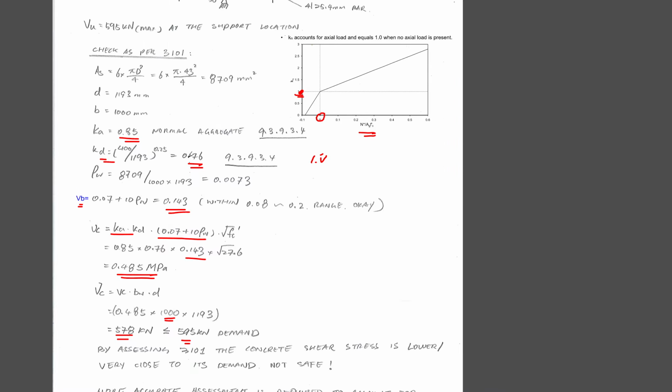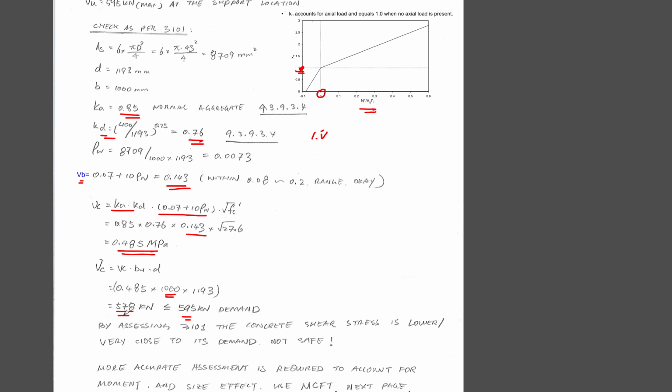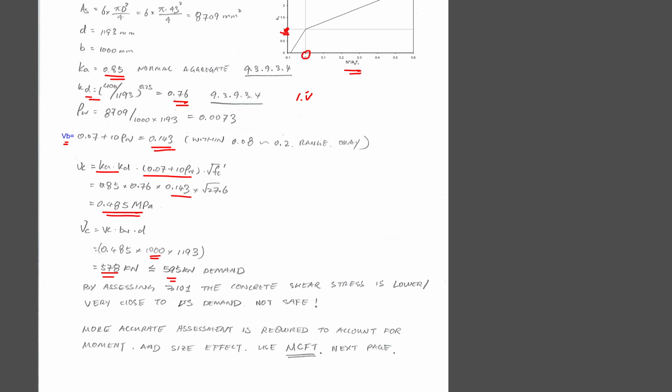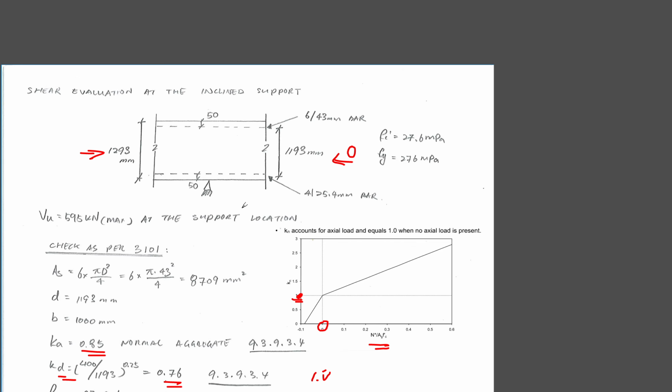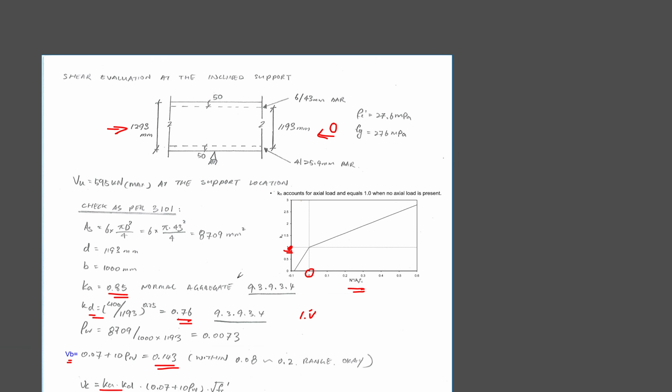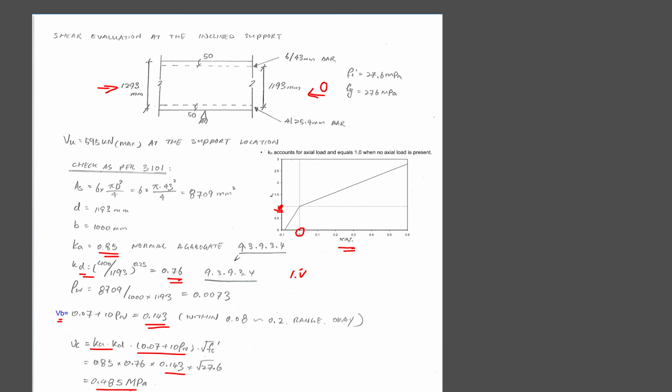interesting, because back then they were probably thinking about Ka. If you used Ka as 1, you would probably end up with the same amount of capacity and demand. So back then they were saying that okay, relying on the concrete shear strength is probably okay. The other thing is that the concrete shear capacity has to be tested, right? Back then in a laboratory environment, if you were going to test small-scale concrete, it's not necessarily reflecting the actual behavior of actual concrete.